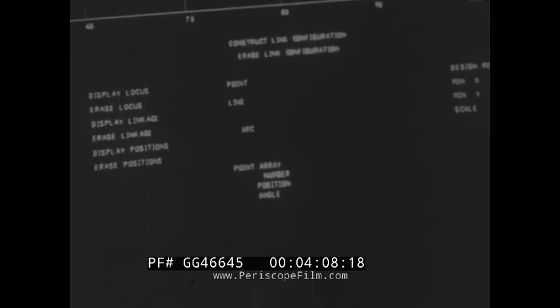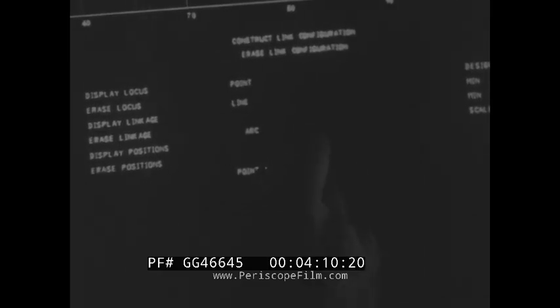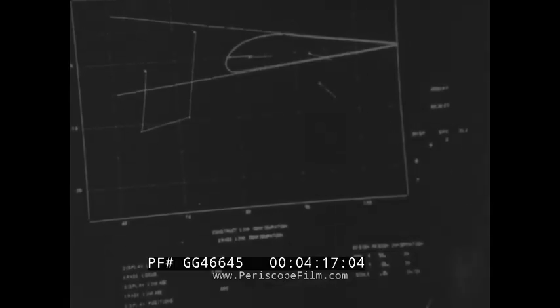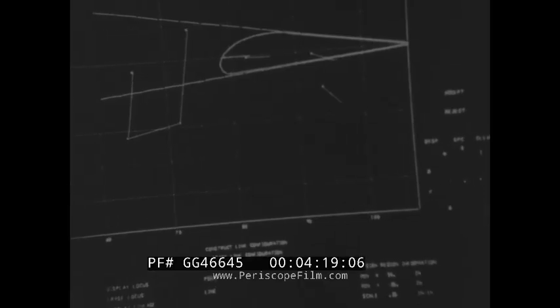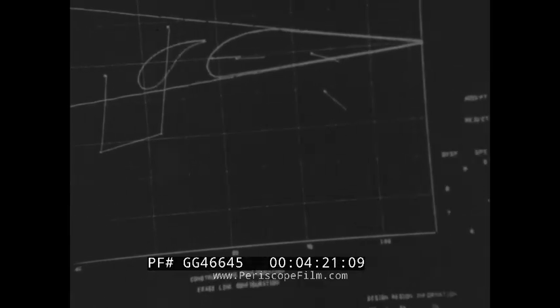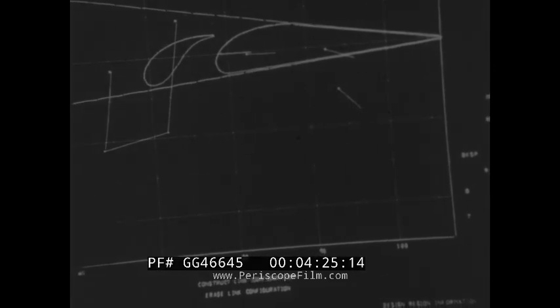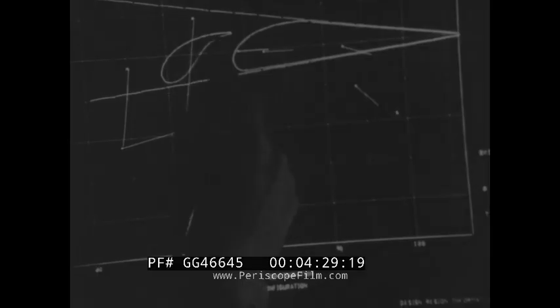The construct option allows drafting to be done about the link center lines obtained from the curves. Points, lines, arcs, and special figures can be drawn quickly and easily. This construction represents a single-slotted airplane flap configuration. Each item constructed is identified with one of the 4 links for animation purposes. The leading edge is drawn using the special figure feature of the construct option. The components of the flap have been specified to move with the coupler length of the 4-bar linkage.